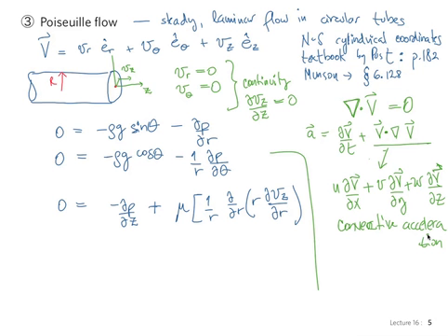All the different cases. We looked at the geometry characteristics, and we're able to cancel out some terms because we think about steady, we think about the flow not having convective acceleration, and we immediately know which terms to cancel out. So you see here, all of these terms in the left are 0 because there's no local acceleration and there is no convective acceleration. All of those terms are 0.